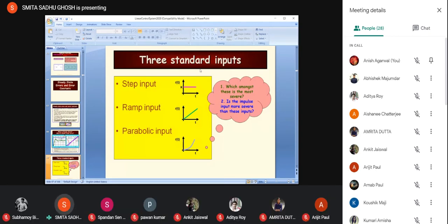It's not because step responses are easy and the teachers are trying to get away with doing something easy. It is because the step input is a conscious choice to see what effect an application of an instantaneous input on the system, and then keeping the input at the same value, would have on the response of the system, compared to the case where you opt to increase the input gradually, namely the ramp and the parabolic input.